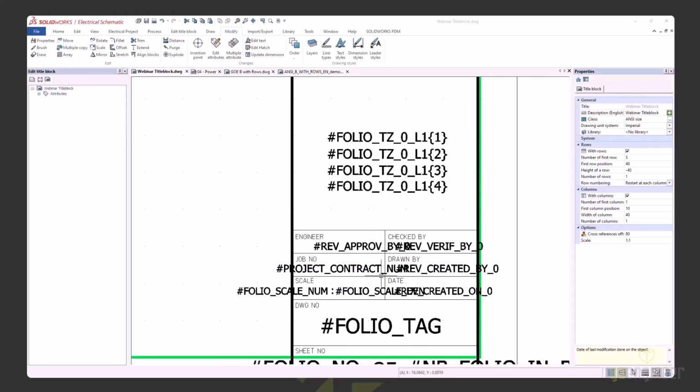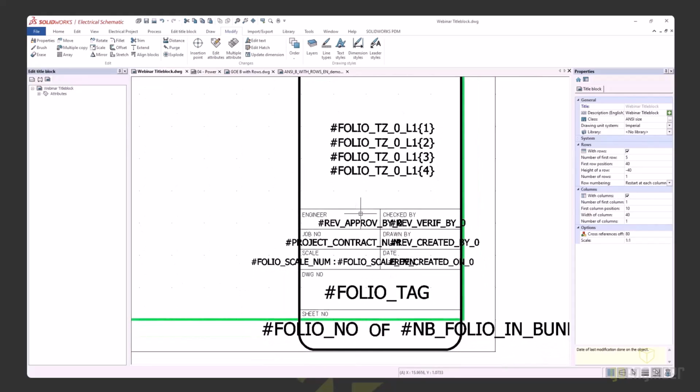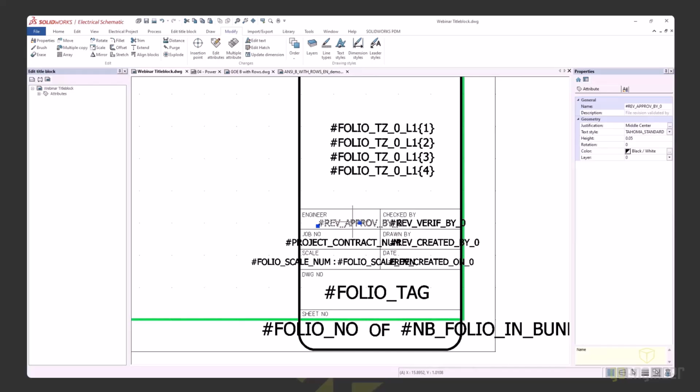Okay, so from here, you can also do things like, when I copy a specific attribute in, you can do something like copy properties, and with those copy properties you can then right click and say apply copy properties. So all the information from the right as far as how it's justified, the height, the color, you can then control very quickly. So if you have lots of attributes that you are wanting to always be the same, you would be able to use this copy and apply.